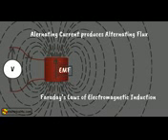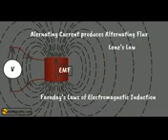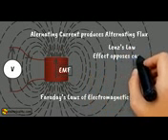Supplied alternating voltage causes alternating current in the winding, which produces continually varying flux inside and outside the winding. This continually varying flux produces induced EMF across the winding. So we can say that the supply voltage is the cause, and induced voltage in the winding is an effect of this cause. Hence, according to Lenz's law, this induced voltage will be in opposite polarity of supply voltage, since, according to Lenz's law, effect always opposes cause.